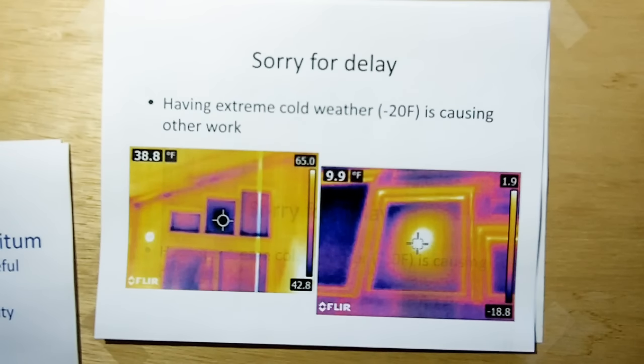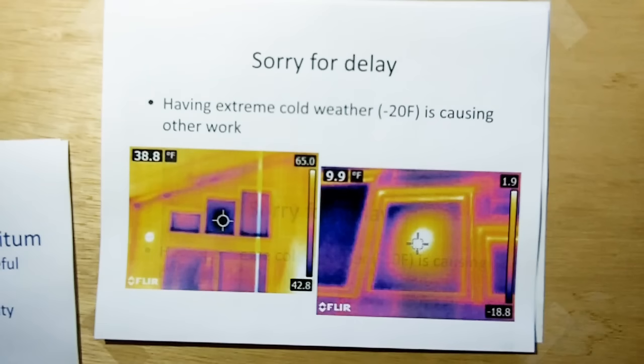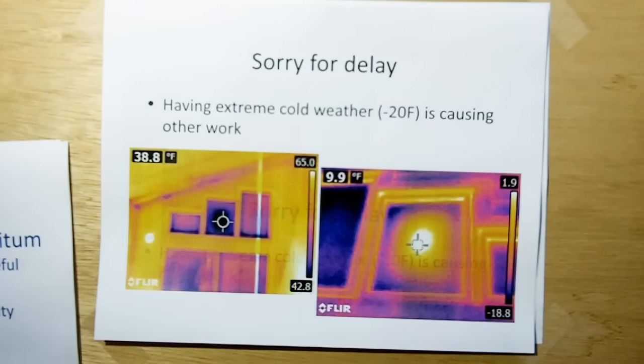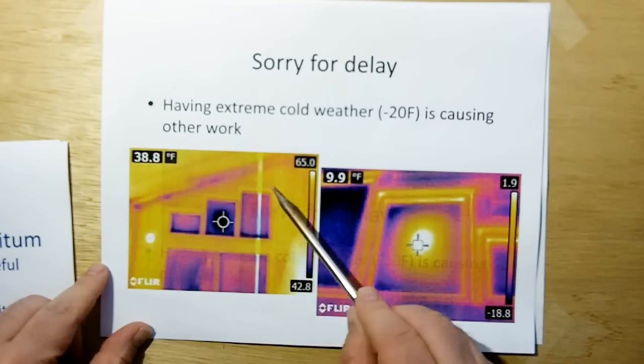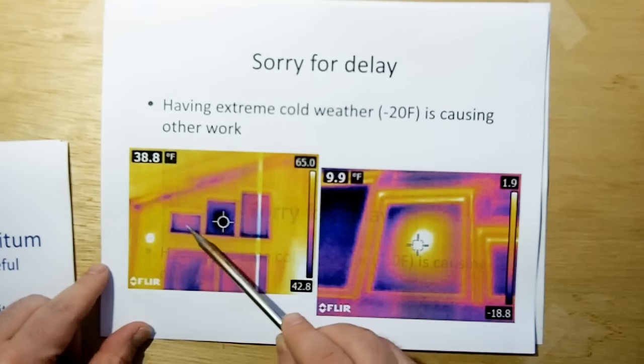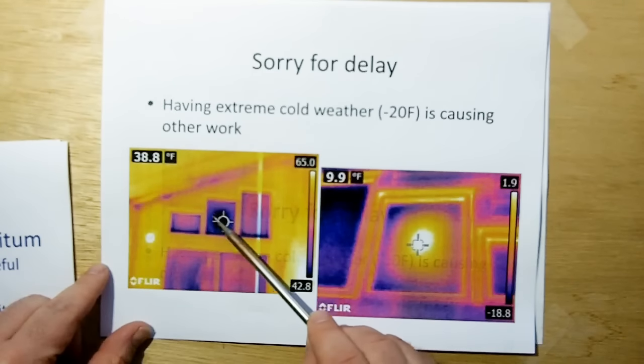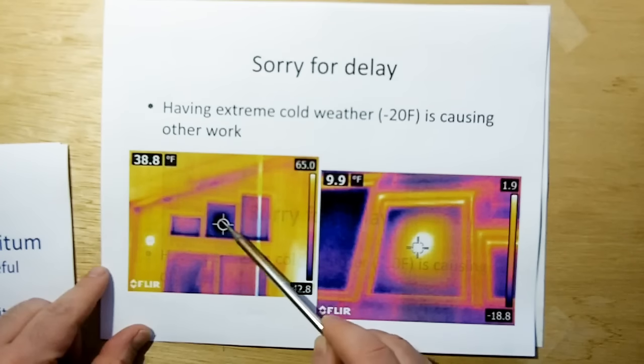For example, the oil burner's on pretty much all the time, which means I'm burning through a lot of fuel right now. So I've got my thermal imaging instrument out to find out where I'm leaking heat, and I find out that I have windows that have failed. They're not broken or cracked, but you can see these are the gable windows here. This is an artifact in my printer here. You can see the magenta, meaning these windows are all doing pretty good. This guy here is completely dark, absolute black in the middle, which means this window has failed.